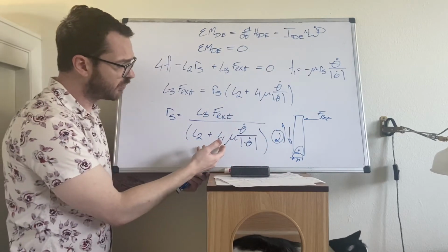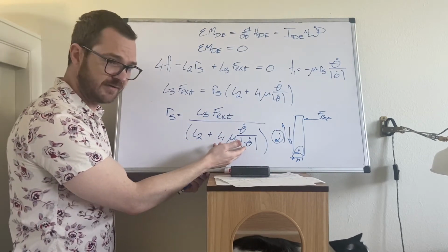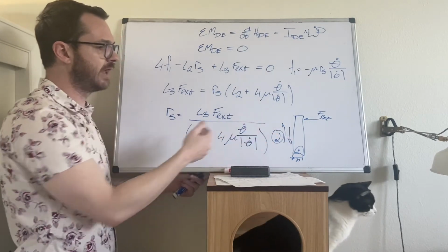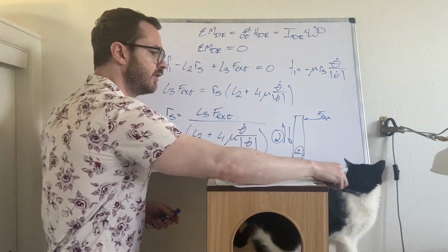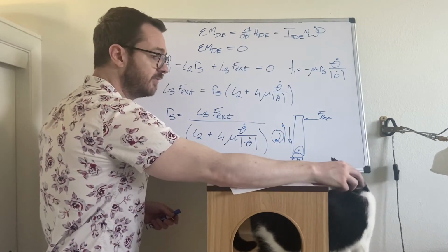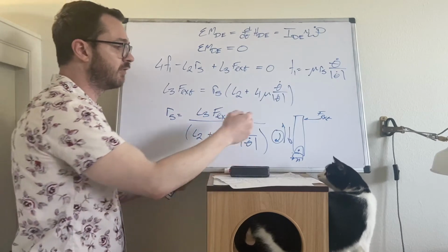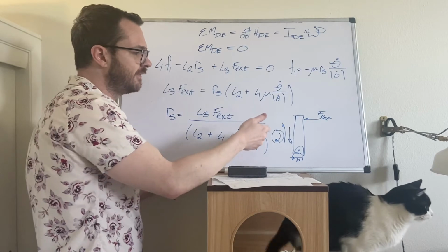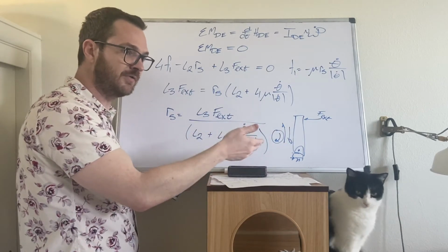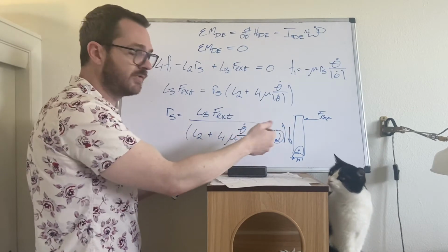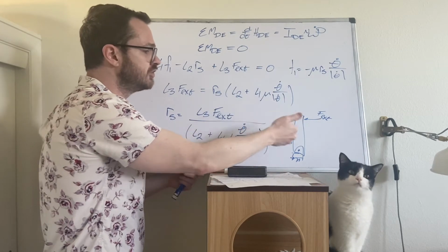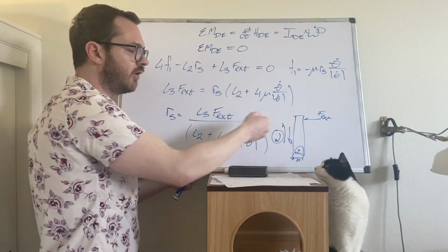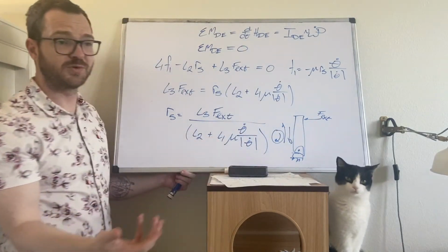So there are times when the rotation of the disk can actually lend itself to the handbrake, or the rotation of the disk could oppose the handbrake. So if you're in a situation where you are designing one of these systems, and you have a choice on which side of the disk to apply the handbrake, understand that if you want the handbrake to be effective, there is a correct choice. Assuming that both options are available, you choose the side of the disk such that the friction actually pulls the handbrake onto the disk, if that's what you're going for.